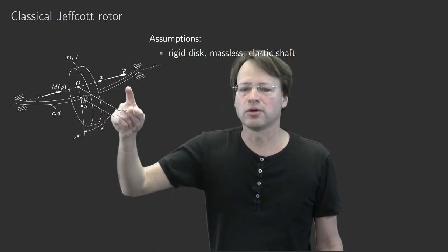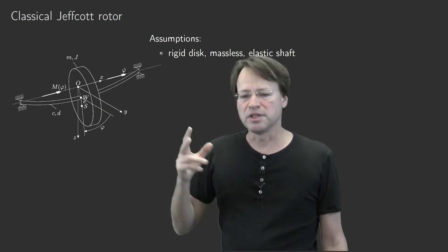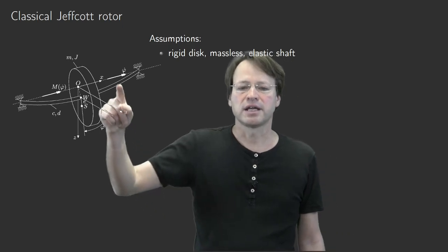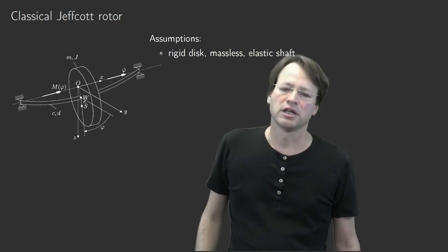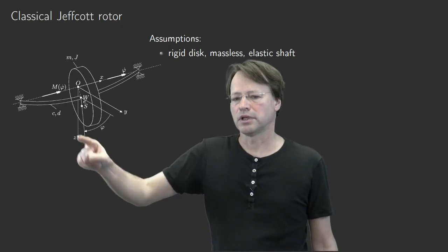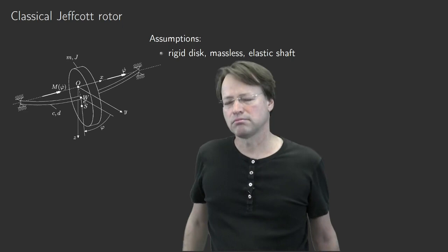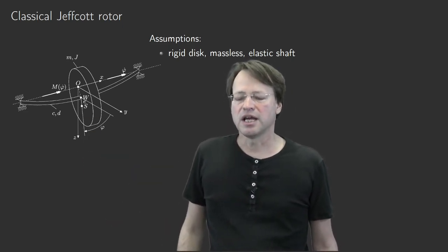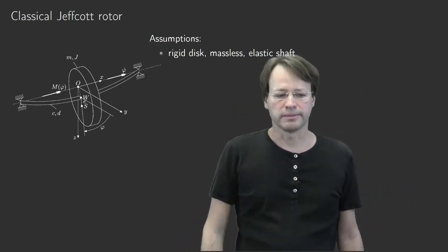And then you can see that on the opposite end we also have a shaft which is to be assumed to be the same as the first shaft and is modeled also as a spring and a dashpot damper. So on both ends of that disc we would have then a shaft, and we can then of course also summarize these 2 springs into one element with stiffness C and damping D. So basically this would be the model.